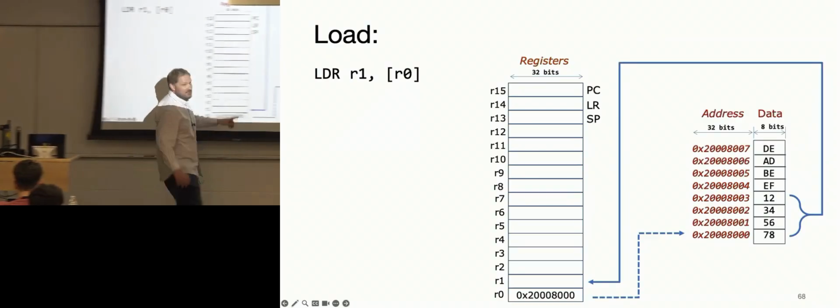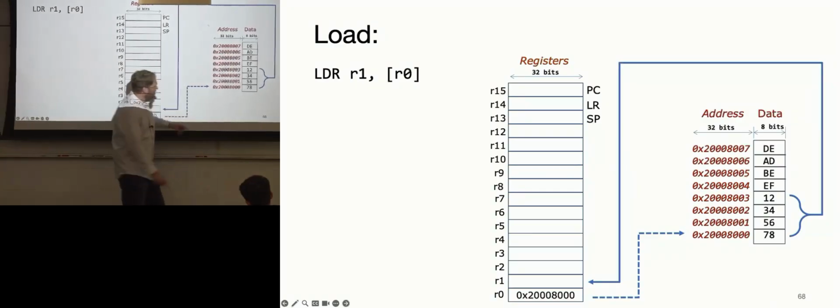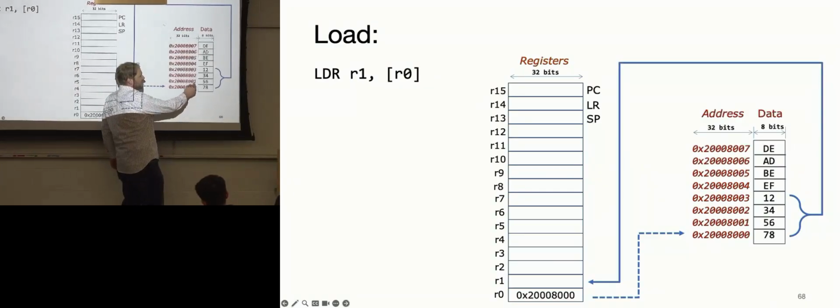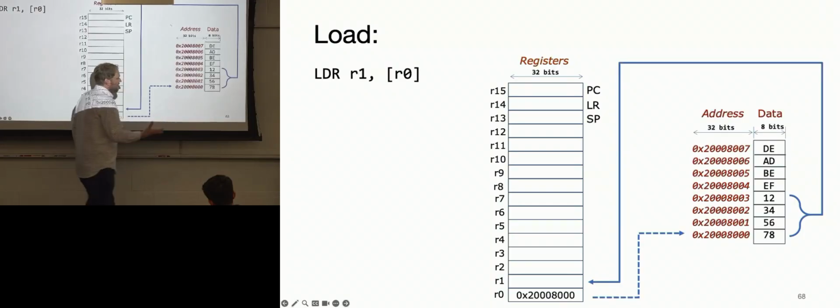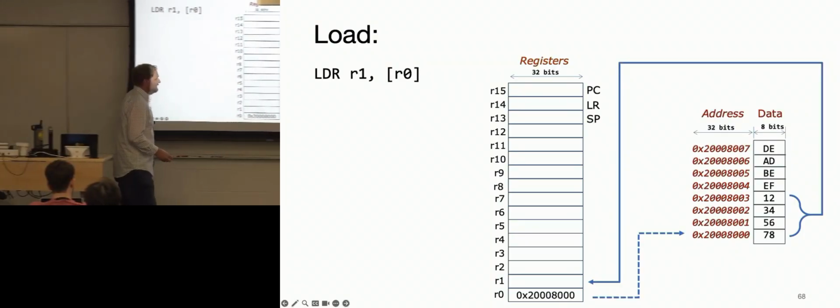Now you notice that here I'm being tricky to you, right? So here I'm incrementing by 1, which means these are all byte addressable, okay? If I had incremented by 4, then it's still byte addressable, but this would represent an entire word. Here it represents a byte. And I'll try to be consistent by putting the extra zeros there if it is a word